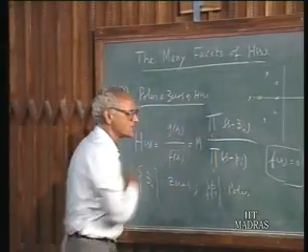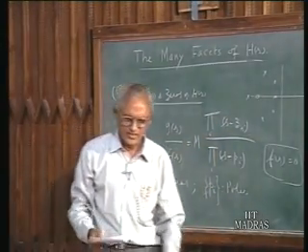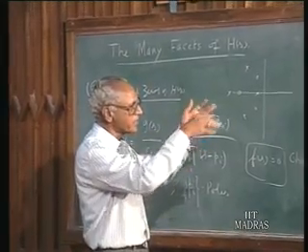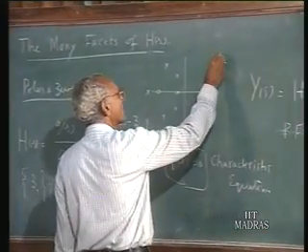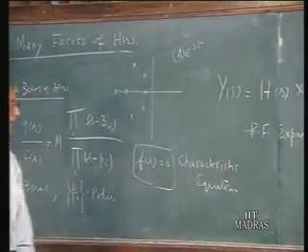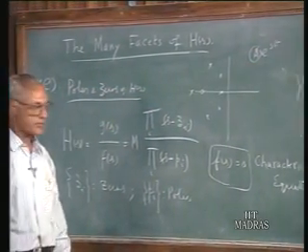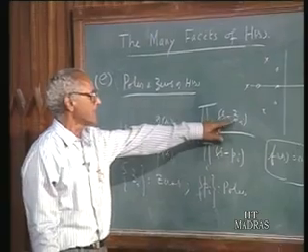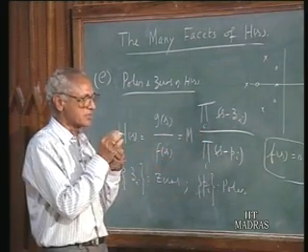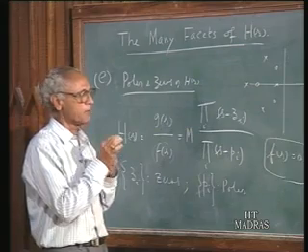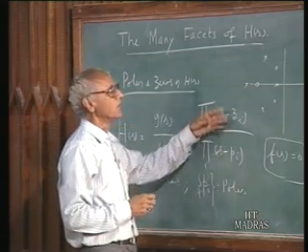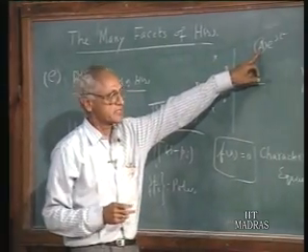As far as the zeros are concerned, they don't have any particular connotation like this. They only vary the amplitude of these various components. Suppose one particular response term is A e to the power of st. The amplitude, or the multiplying factor, of the complex frequency term is dictated by the zeros. The poles, however, represent the modes, the complex frequencies in the time expressions, whereas the zeros will only vary the amplitude of the various terms.